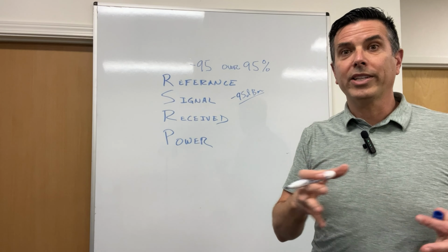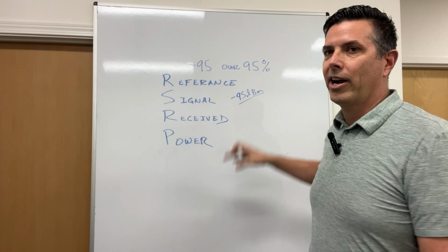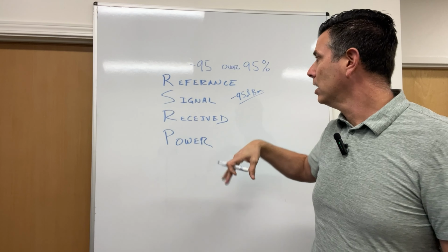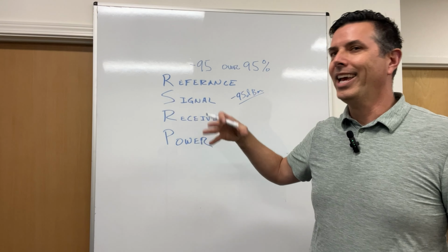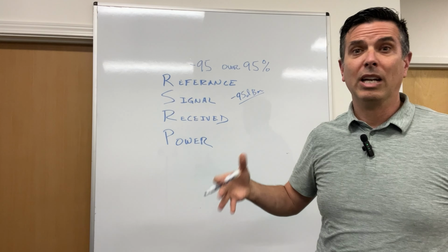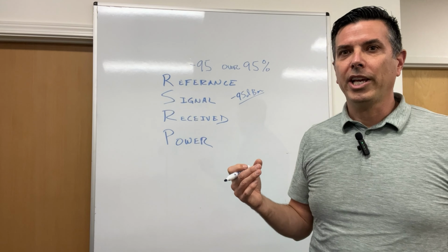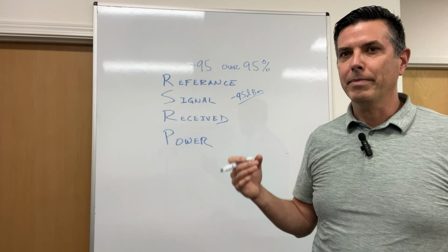As you get closer to zero, that's a stronger signal. As you get further away from zero, it gets worse. So it'd be lower and lower technically. If you're neg 105 or better in an LTE system, you're going to be fine. It's a little bit more sensitive when you get to 5G. You're going to see about a 10 dB metric, a little bit better.